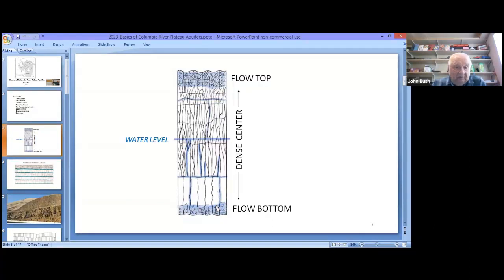That fits what Steve Rydell says, that the flow has a dense center, and it leads to the confusion of that flow, the low flow, being considered both an aquifer, because you can get water out of the saturated zones, and an aquitard. In other words, a layer or a portion that is almost impervious, and the aquitard prohibits easy exchange, easy percolation, from top to bottom. So we have to remember that a basalt flow, any individual one, can be both one or the other.